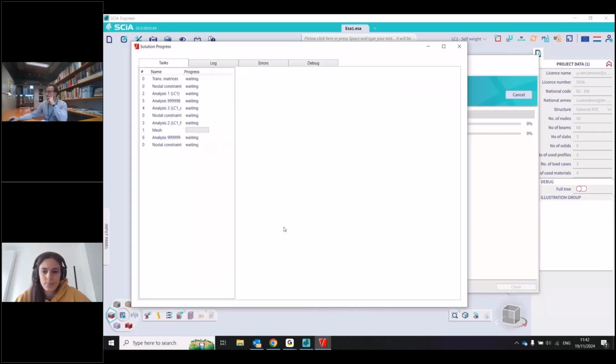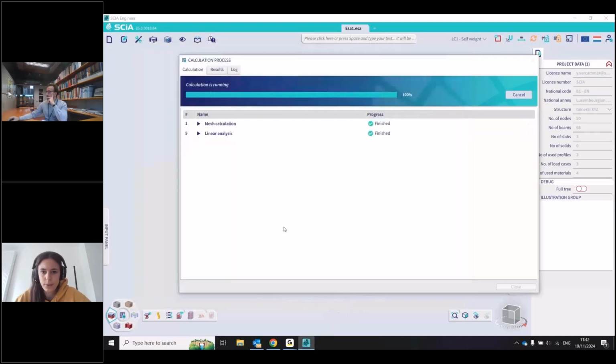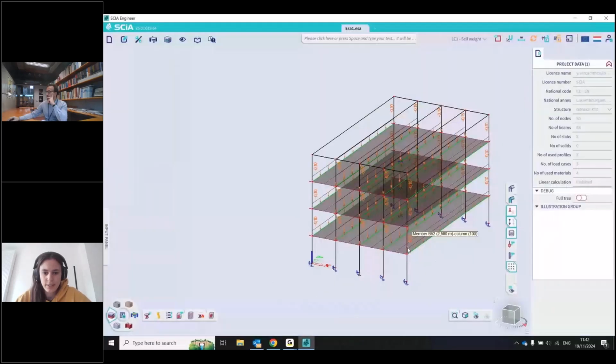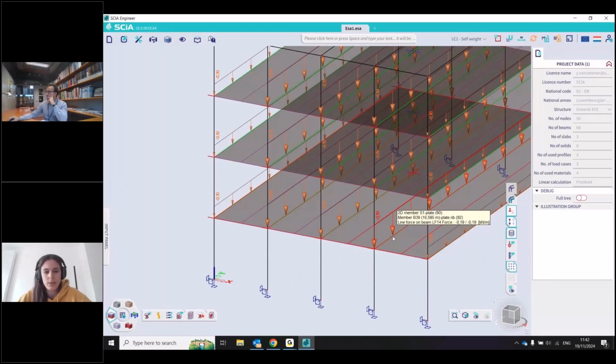There we go. So now you will see that the effective widths are more logical. This one gets this half. The ones in the middle get the two sides of them. If there was more spacing in between, maybe the effective widths wouldn't be touching each other, but in this case, they are. So I guess the full composite deck is being used here.